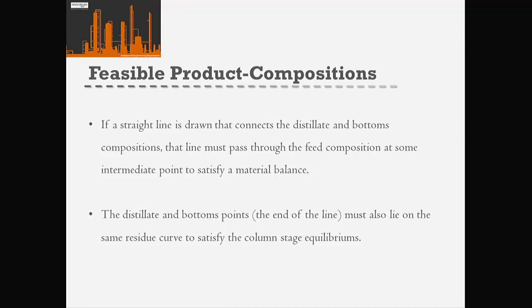Okay? So we also saw that our residue curves are related to the vapor-liquid equilibria. You can think about that as the actual stages in the distillation column.